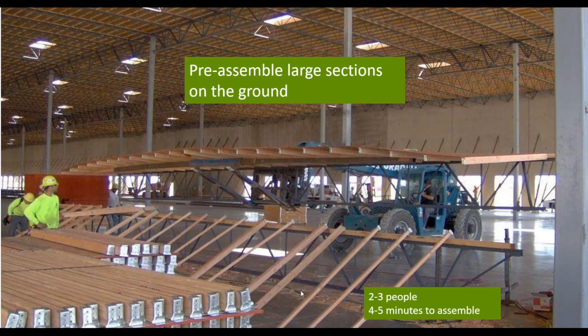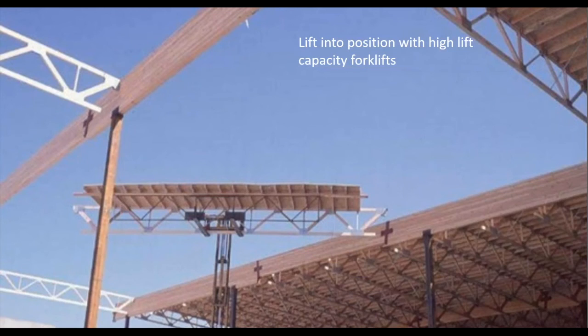For those that are not familiar with panelized roof systems or pre-assembled roof systems, what you see here is an example of one method of doing it, where we have the framers on the ground that are assembling these. You see the sub-purlins here, 2x4s or 2x6s that are set into place. And then we have the steel bar joists here that support this pre-assembled assembly. That's constructed on-site, on the ground, which is a very safe way of constructing it. And then it's lifted into place.